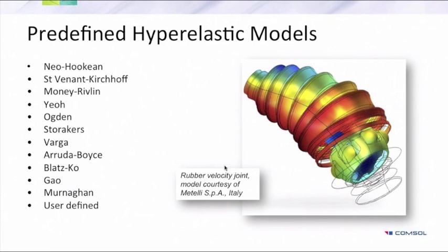The hyperelastic models depend on energy formulation. Here again, there are many models which are implemented in the Nonlinear Structural Materials module. Additionally, there are three Mooney-Rivlin type models, the 2, 5, and 9 parameters. The example of this type of models is the rubber constant velocity joint that undergoes severe deformation, but upon unloading, it will go to a stress-free state.